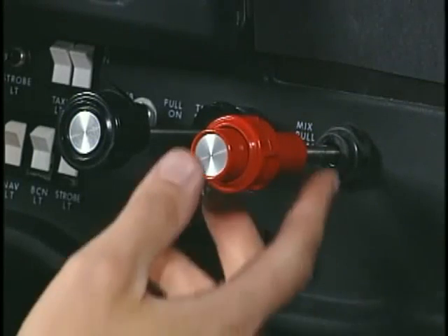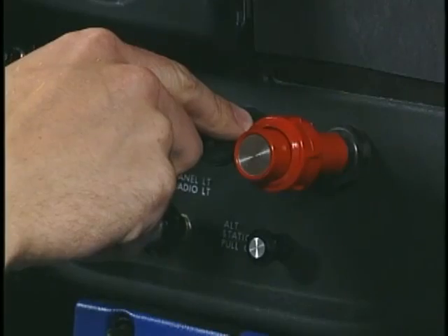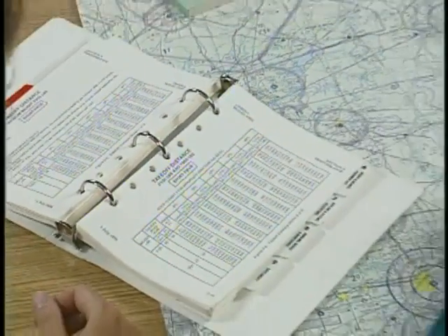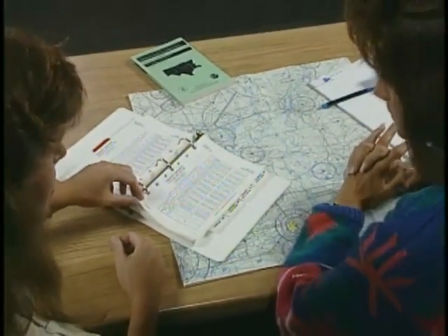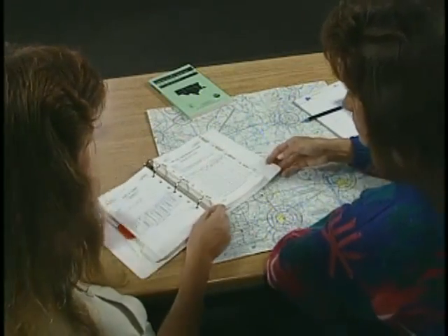You can also point out that a richer mixture may be required and fuel burn will increase with flight at lower altitudes. Regardless of the pilot's previous experience, it is essential to review the performance charts in the pilot's operating handbook. If the pilot has been operating at one airport for an extended period, it may have been some time since the pilot analyzed performance data.